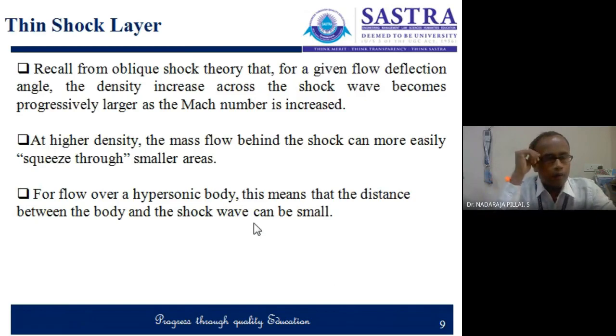Okay, let us recall the oblique shock theory we have studied in compressible flow, probably Modern Compressible Flow by John D. Anderson or Gas Dynamics by E. Radhakrishnan. You have studied that in the fifth semester or so. We know that there is an increase in density across the shock wave when there is an increase in Mach number. So we say that at a higher density, the mass flow behind the shock can more easily squeeze through the